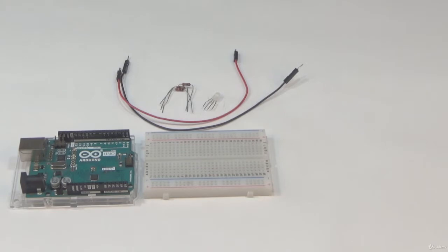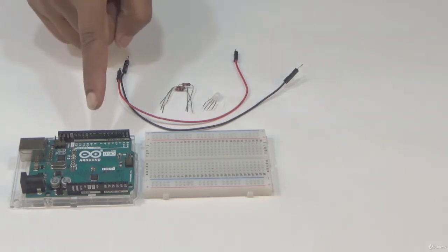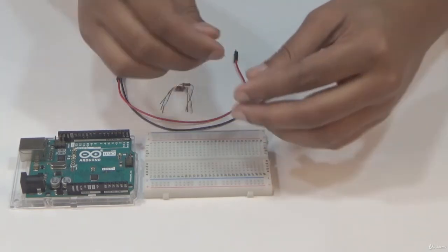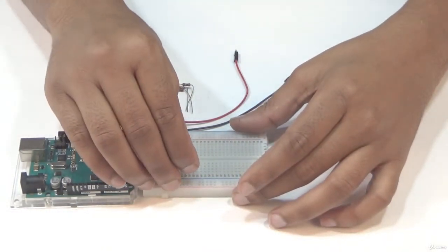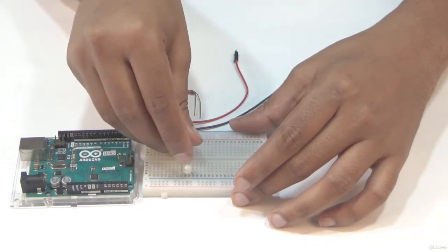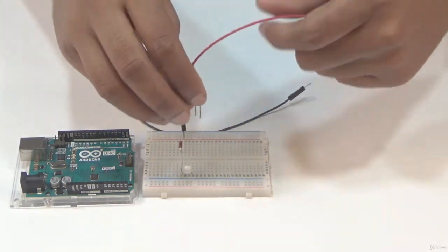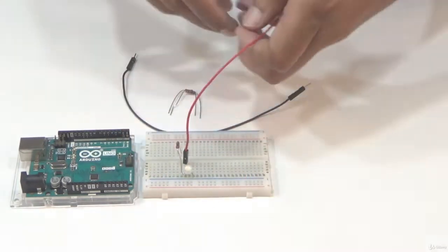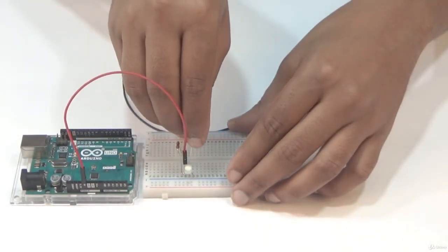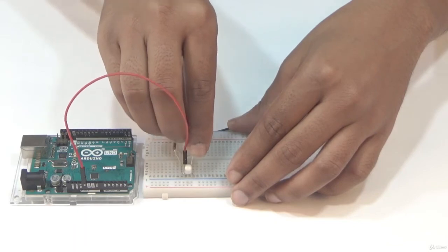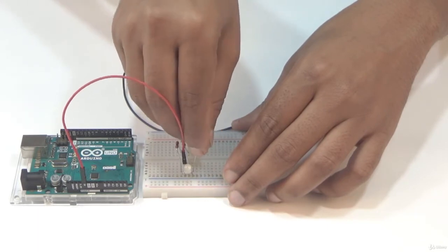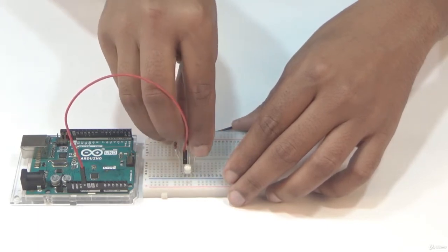Here I'll show you how to test common anode RGB LED. The Arduino board, breadboard, RGB LED, resistance and wires I have. So let me put this common anode RGB LED on breadboard. I have marked the common. So I am connecting resistance at the other terminals. And at the common terminal, I am applying 5 volt. I am connecting it to 5 volt. Then I will power up the Arduino. Then connecting resistance at RGB LED. Remember, this is a common anode RGB LED.